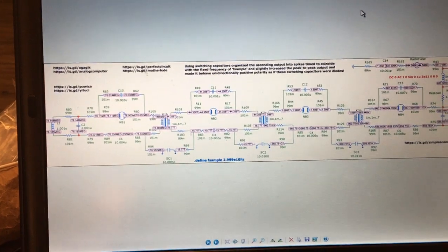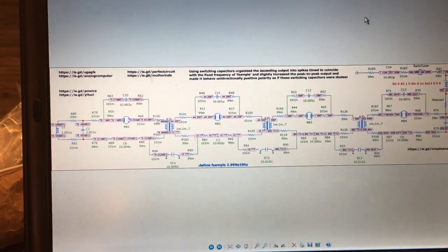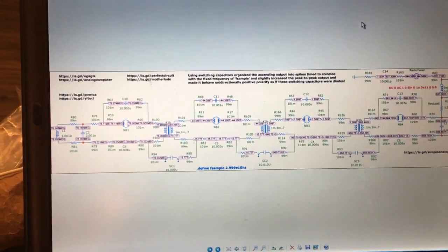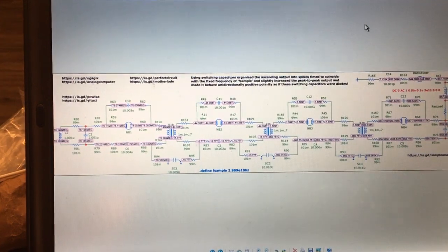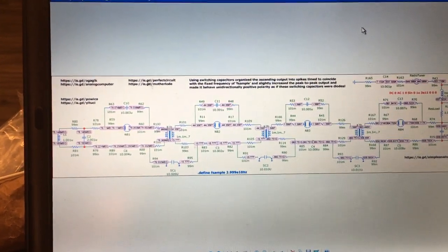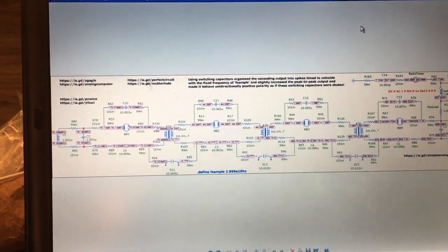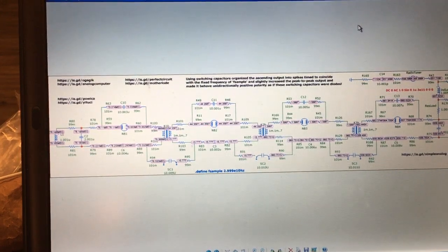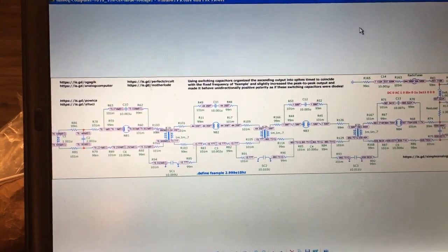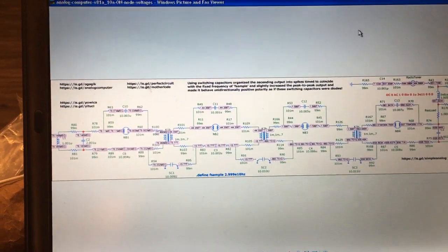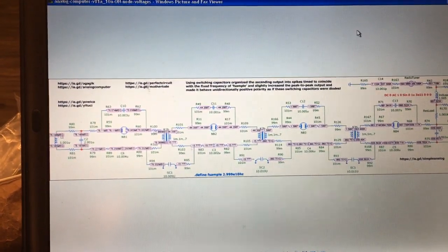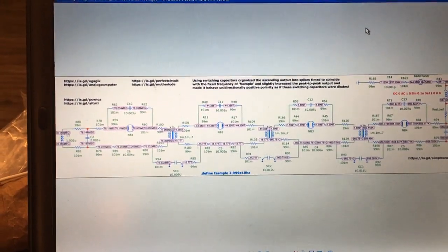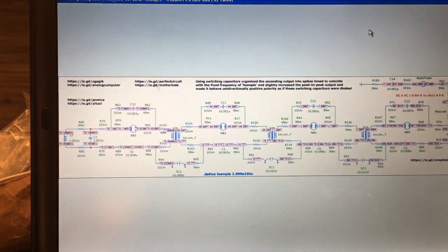Okay, so here I did 4 versions because instead of it diminishing the output, it actually increased it, and it made it unidirectional in a positive polarity on the virtual oscilloscope tracing. It seemed to suppress the buildup, and that's why the peak-to-peak spikes got bigger. Why they went unidirectional, I have no idea. It's almost as if it recoiled, but it did so at a particular frequency, the frequency that I set the sample rate of the switching capacitor at.